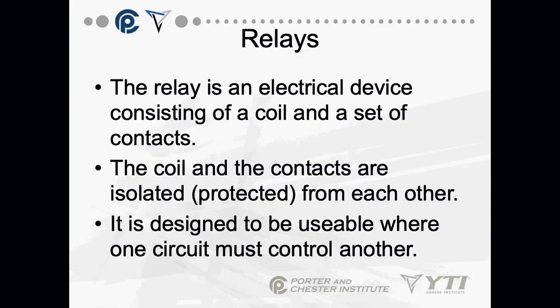So the relay is an electrical device that consists of a coil and a set of contacts. The coil and contacts are isolated from each other. There's no electrical connectivity between the coil and the contacts. It's designed to be usable where one circuit must control another.